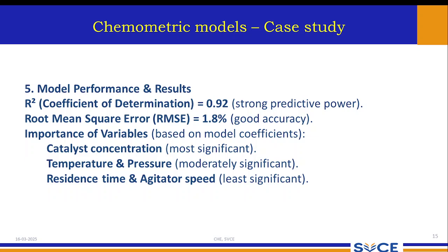Okay, because this is coming under the CSTR. So what is the principle behind the CSTR? At any period of time, the concentration inside the reactor is equal to the concentration outside the reactor. But the residence time talks about how much time the fluid element has spent inside the reactor. That you know already. So if the fluid has spent much time, or even leaves the system by shortcut, it doesn't have much effect on the product formation. That you need to understand. So that's why I say it is the least significant.